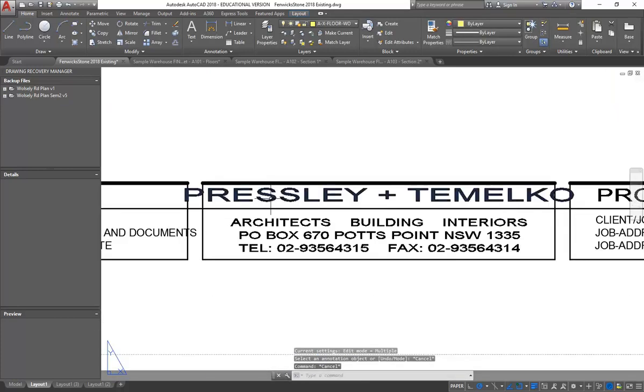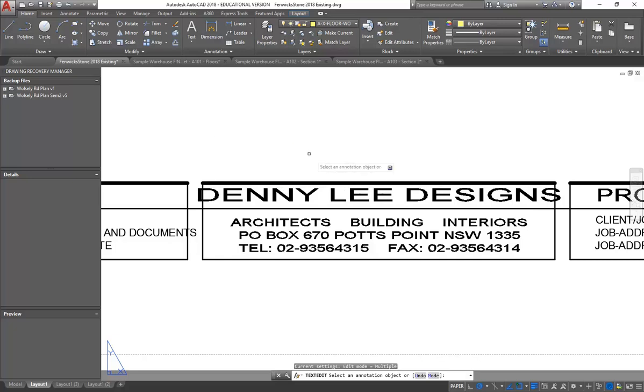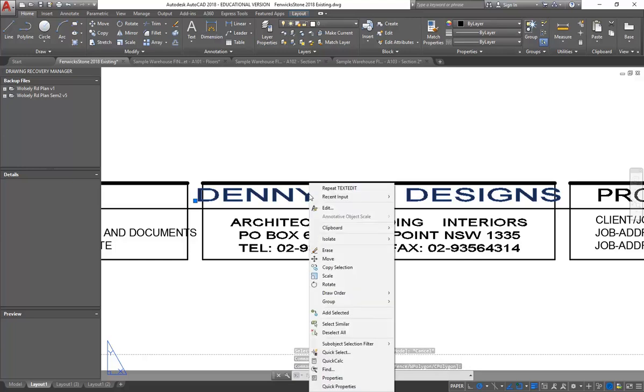So coming back over here, so I'll put in, okay, so you can put in whatever you like there, and maybe it's a chance to reformat it. So do you remember the easiest way to reformat things like text? So we can obviously double click to change the text itself, what's written, but then to change any of the properties or the format, remember the easiest way is to select, this works for anything, but definitely for text, select the text, right click, and go to properties.